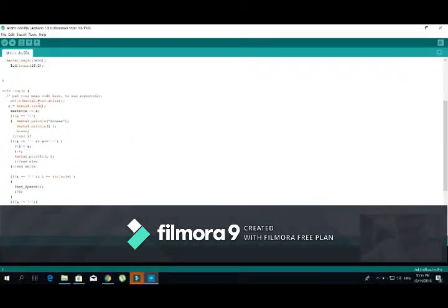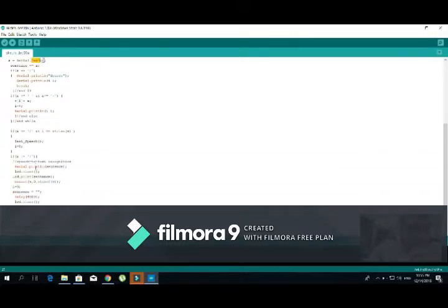We also use the serial for the speech input. We connect the Bluetooth module to the RX pin in the Arduino. By using serial read, it reads the bytes that are sent to the Bluetooth module, and each character, sent in an individual byte, is added to the sentence string. After the sentence is all sent, the LCD clears the sentence that was written before, and then prints the string sentence.